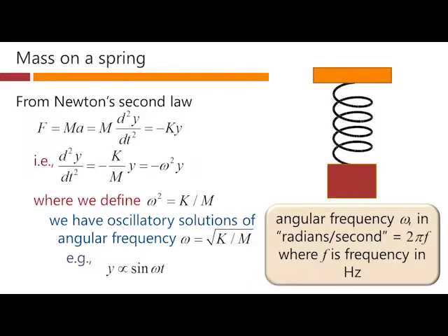And we call this omega the angular frequency. We could use the actual frequency in hertz, but then we'd have to put in a 2 pi f here. But we often prefer just to work with angular frequency. It just saves us some time in not writing down the 2 pi's. So technically the angular frequency is the number of radians per second as opposed to the number of cycles per second. But it just saves us a bit of pencil lead to use omega instead of f.